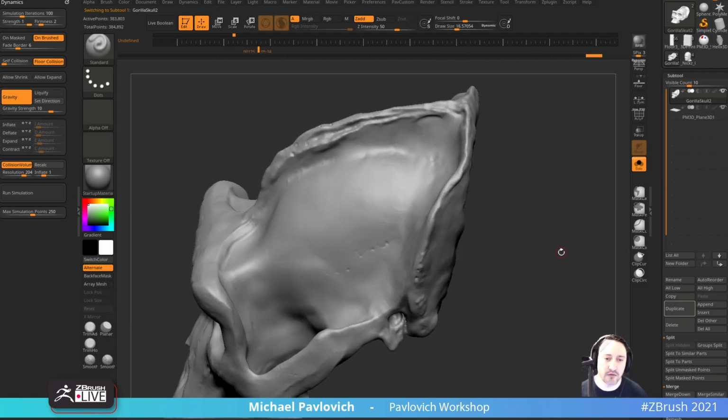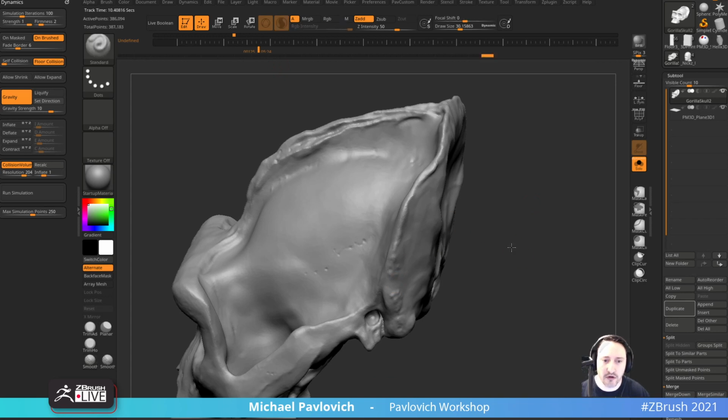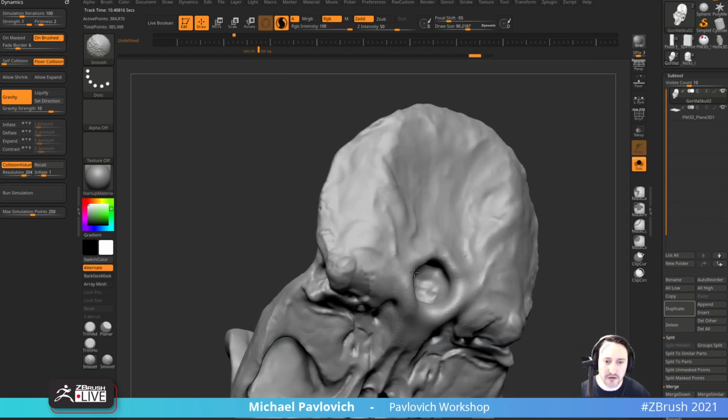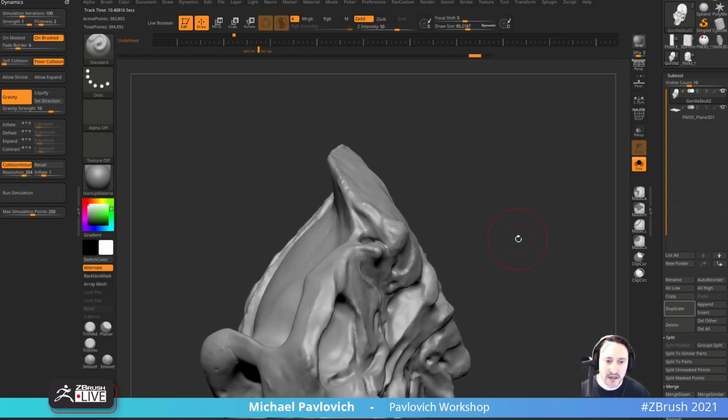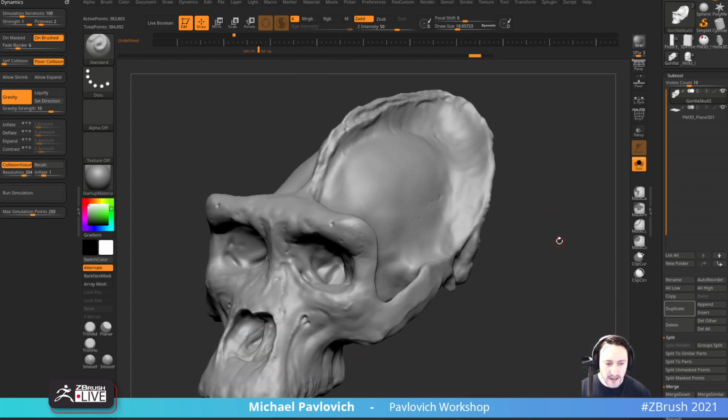If you don't go through there and clean those areas up, and sometimes cleaning those areas up is like we did earlier, just hold down Shift with Sculptris Pro and you can chew away any problem areas that you might have. Otherwise it will build in that flipped and curled geometry, which gets weird and gross. But other than that, no, just Decimation Master is fine.